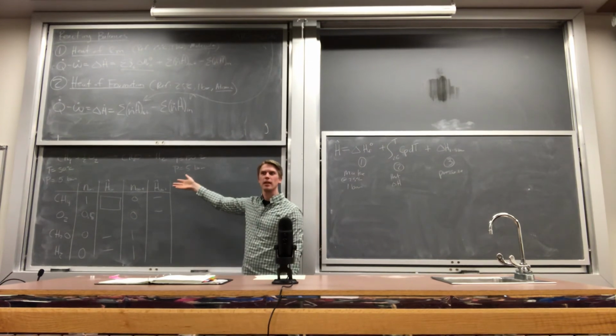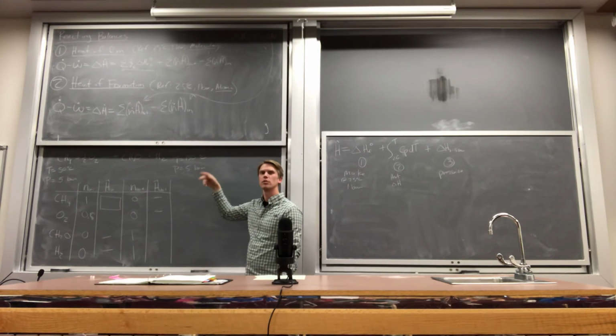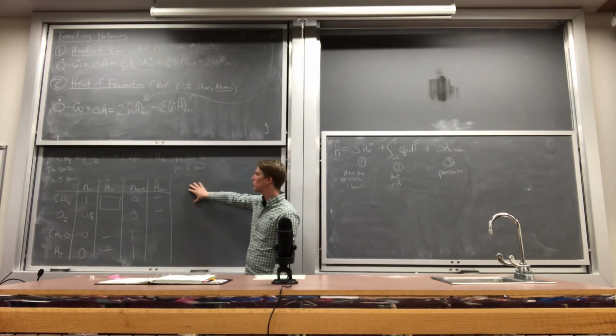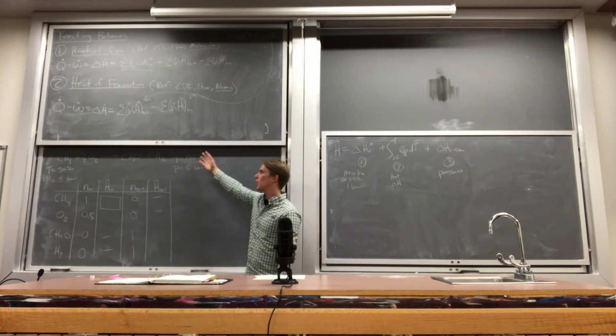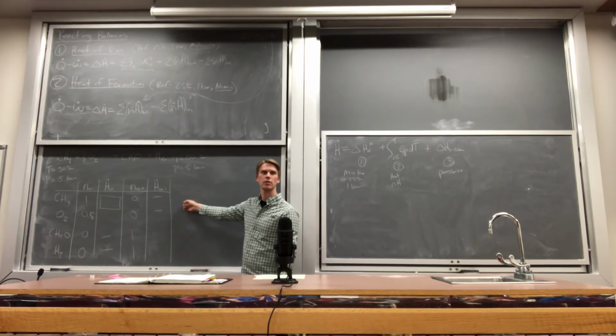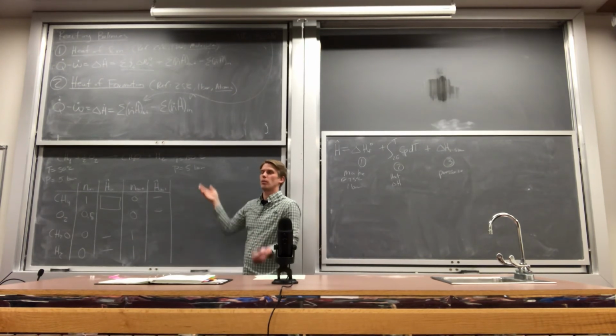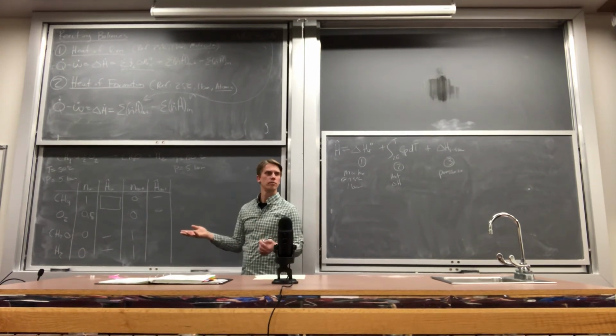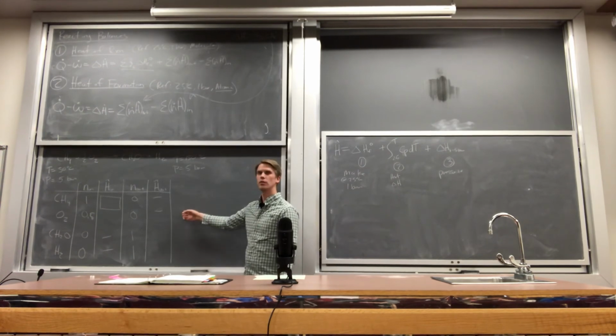It's like an atom balance, kind of. We don't care what reactions happened. All we care about is where are the hydrogens, where are the carbons. In the heat of formation approach, we're just keeping track of the energy coming in and energy going out. So there could be 100 reactions going on. And this is why a process flow simulator is generally written to handle this type of process. Especially if you're dealing with something really complex like crude oil, you don't know what reactions are going on. There's no way you can know. So you just keep track of what's coming in and out.